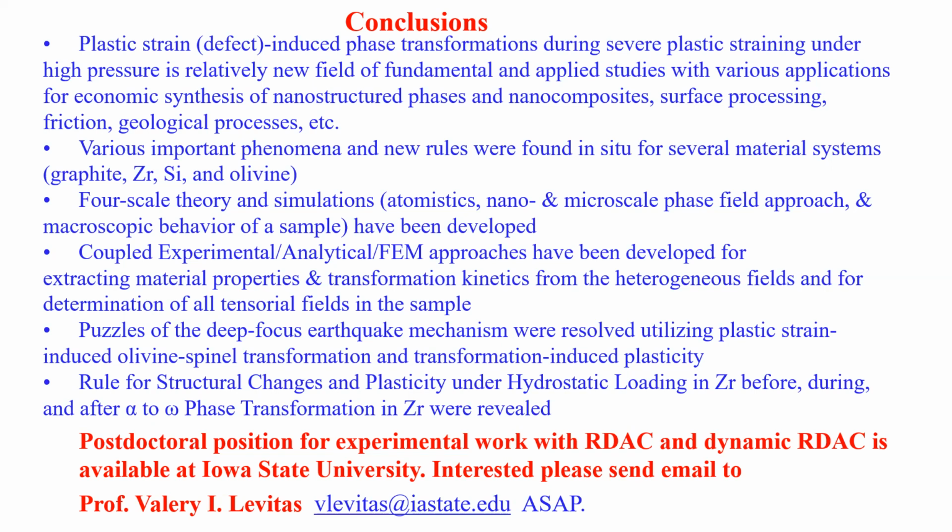And then what does B depend on? What does B depend on, that variation that we multiply? Well, I don't know. This is just an empirical parameter, and it's usually on the order of 0.1. I cannot say what determines this parameter because there are various factors which may affect it based on dislocation theory. First, one explanation is the increase in elastic properties, but it does not tell us the entire story. Most important is a change in dislocation core structure, and it occurs even at quite low pressure.